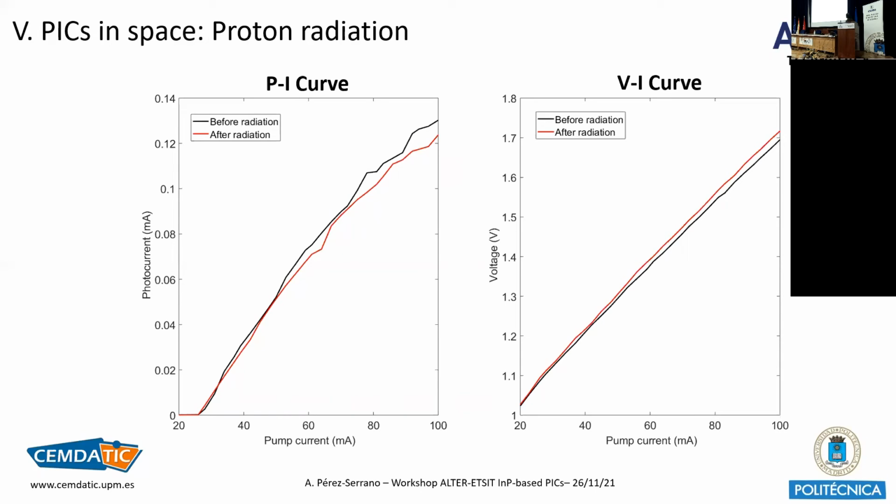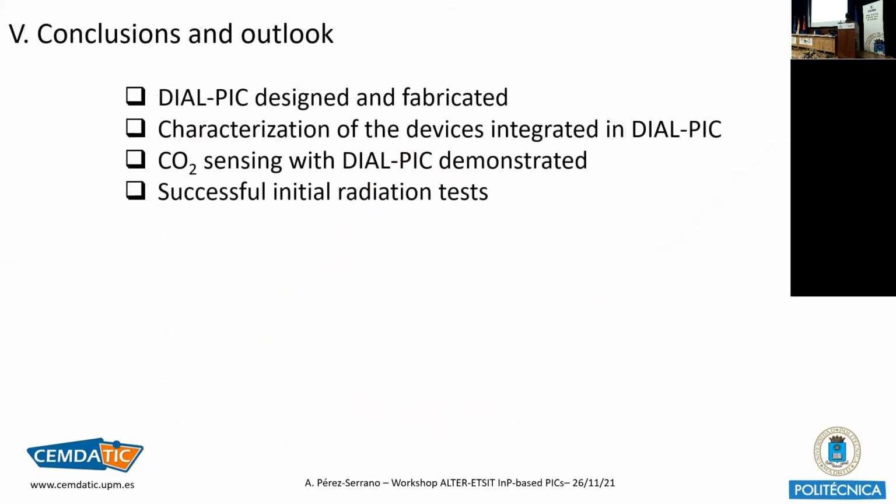So with this, I will summarize. The conclusions are that we have designed and fabricated a differential absorption Lidar chip. We have characterized the devices integrated in the DIAL PIC, and we have found some problems that we expect to solve, but we have demonstrated CO2 sensing, and we have performed some successful initial radiation tests.